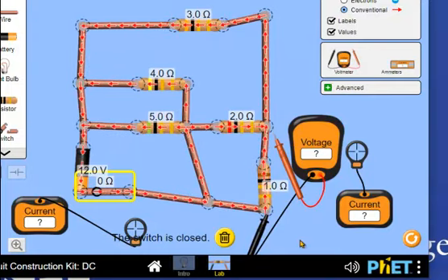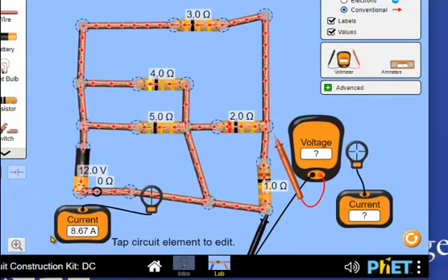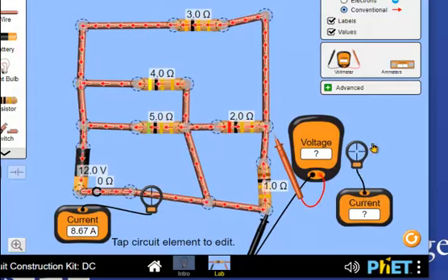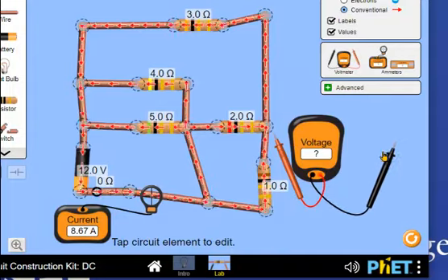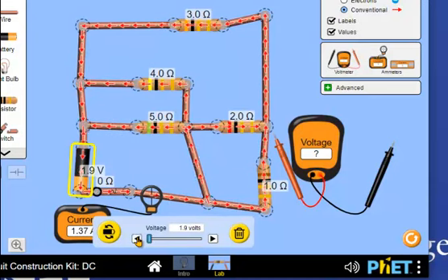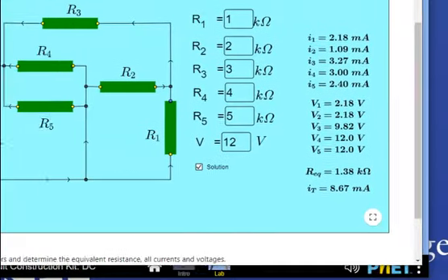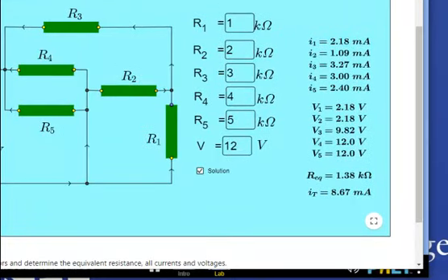So I'm going to do this one again. Oh, actually, I'm just going to measure first. So this here would be a total current just out of the battery. I need this one here. And I'm going to reduce the voltage again until I'm going to get a nice 1 amp. Looking for that here. It's on the lower left, the ammeter. Oops. There we go. That's close enough. 1.01. So 1.4 divided by 1.01 is still about 1.4 ohms, and that's what it says. That's what it should be, 1.38 ohms.